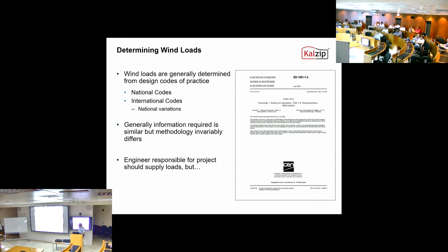We could look at all different loads, different standards applicable to different regions, and we can change the design tools to suit the different regions. But ideally, we also always need to check with the engineer who's responsible for the design of the building to make sure that any loads we consider or work out are representative for the building and for the region.